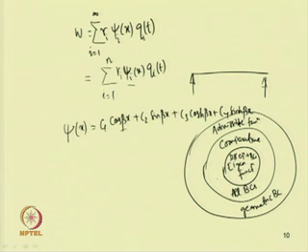If one uses the eigenfunction, then most probably one can get equations which are decoupled, but if one uses the admissible function, which satisfies only the geometric boundary conditions, sometimes one may get coupled equations of motion. Now let us consider different cases. How can one find the boundary conditions associated with this?